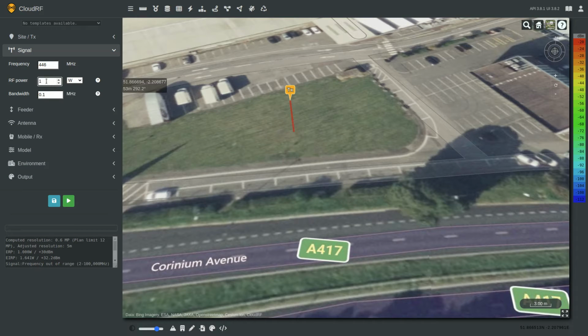The power can be measured in watts or decibel milliwatts if you're doing a low-powered system such as Bluetooth. For now, we're doing 1 watt, which is 30 dBm. And we can use very large values in there. We can go up to several megawatts if we need to.